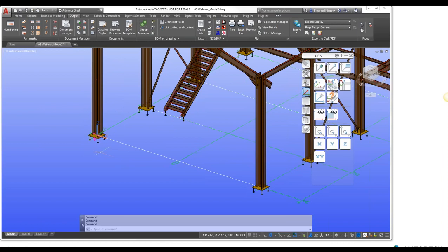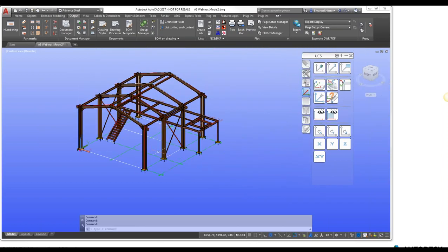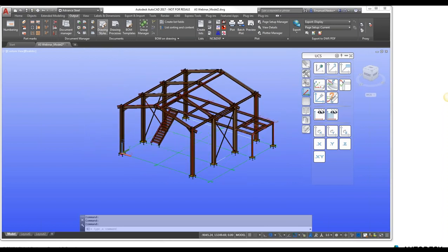So in fact, using the X or Y plane plus the depth, we will have a box from the 3D model that will decide what will be shown in the detailed drawing. This box can be limitless, without any limit, or we can have limits. But in any case, we discuss about a box, not only a plane. Let's try to see how it works.